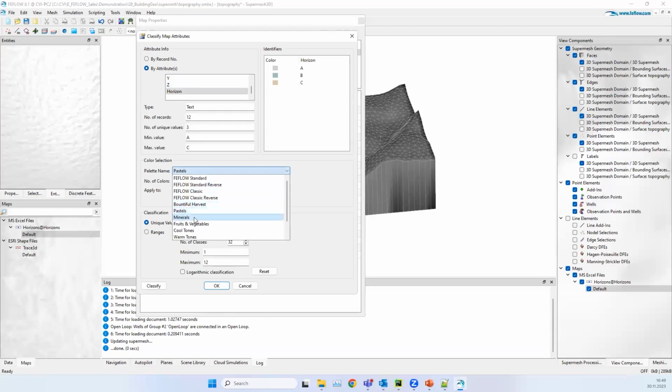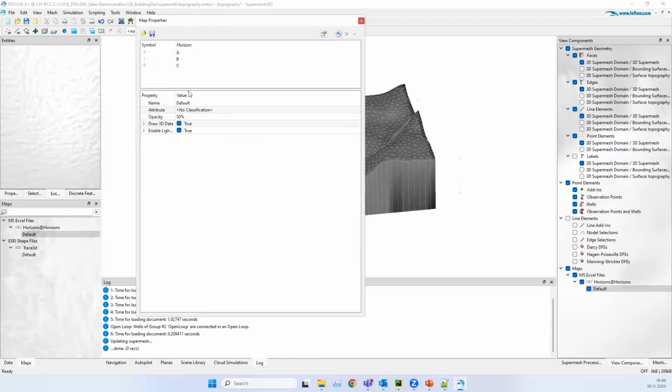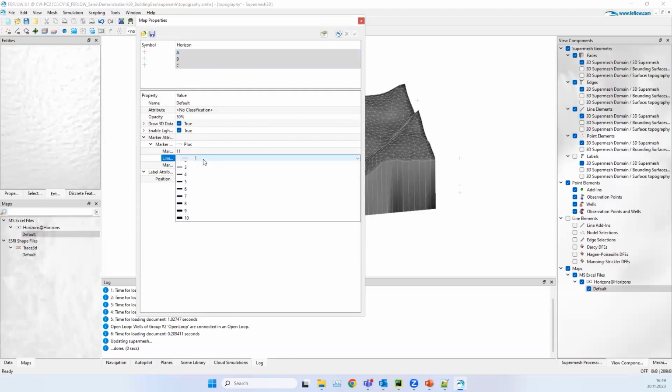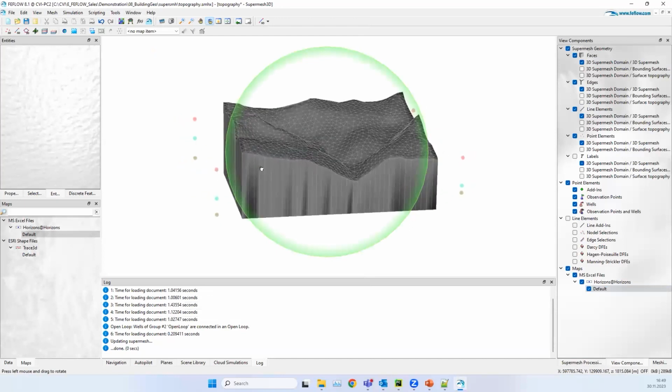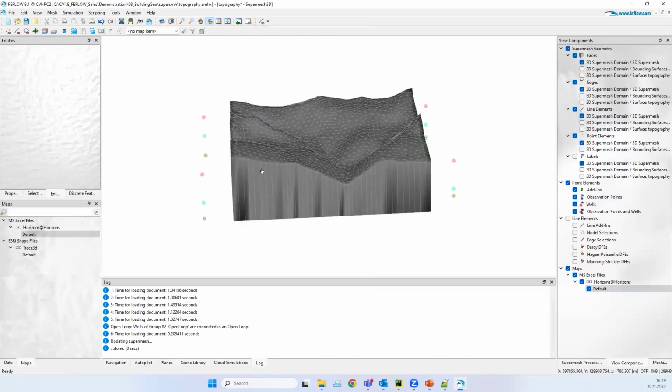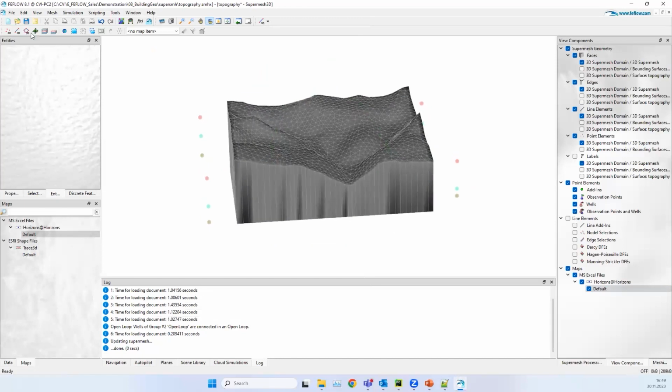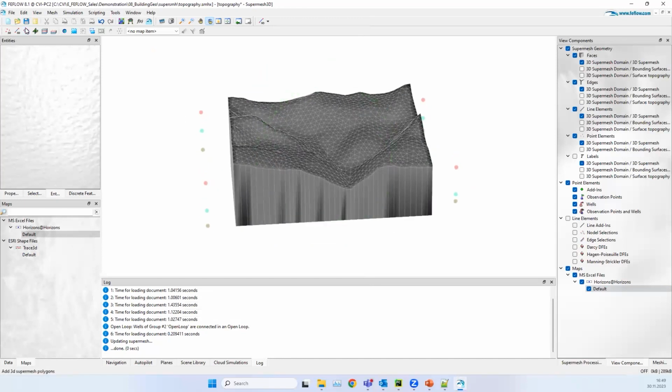So that's not visible. Okay. And let's make the lines a bit thicker. Apply. So we have these points, and these points are defined in certain geological conditions. So we can use our tool, something very simple, to digitalize the surfaces. So we can also tell FEFLOW I would like to snap using points coming from the map.